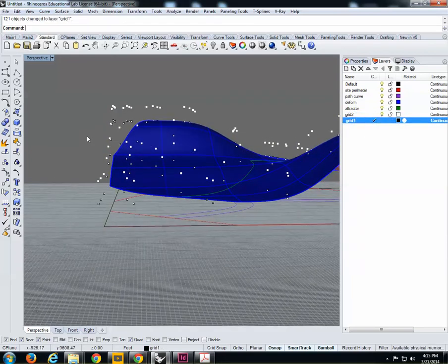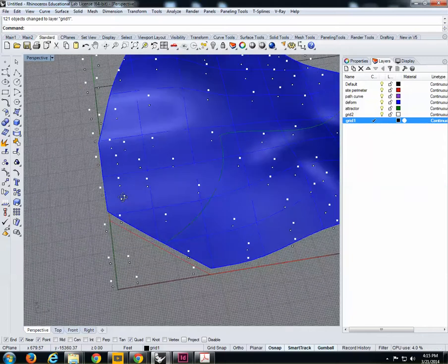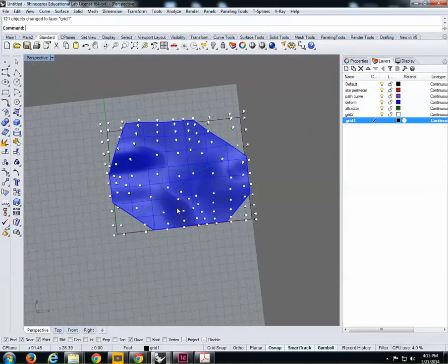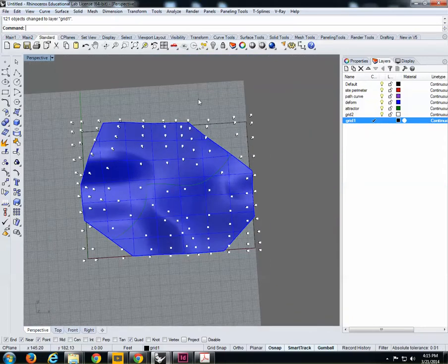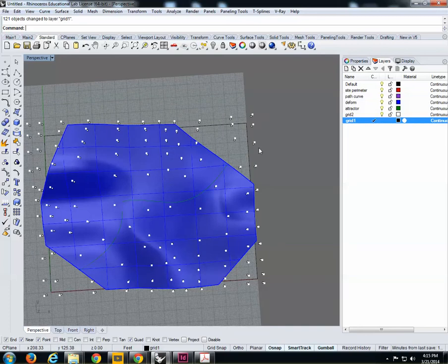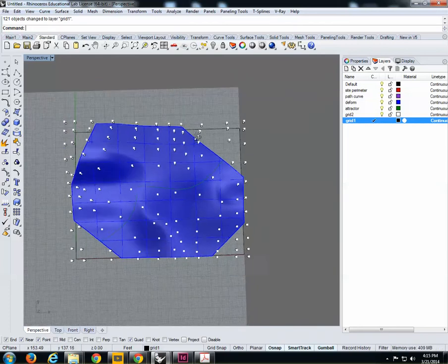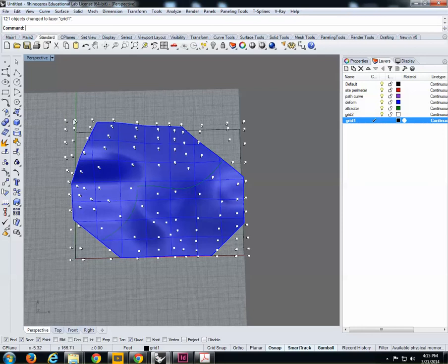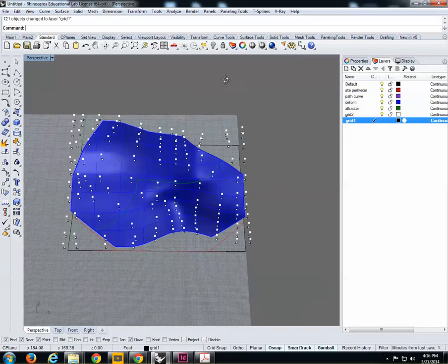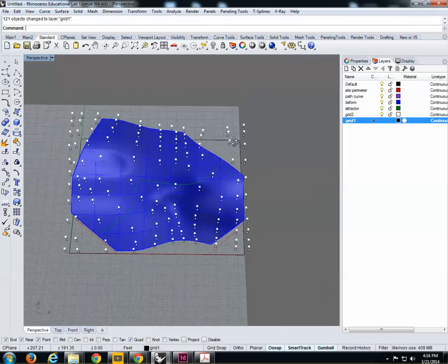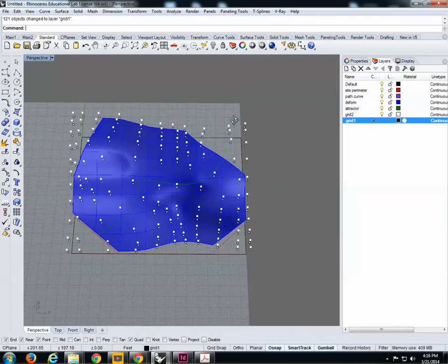Nice. So the next step, it seems, what we are trying to do is to basically get rid of these extra points that are not really describing our surface. So paneling tools go ahead and work with the overall surface that generated this trimmed surface. That's why they end up giving you points of a full rectangle. You don't want that resolution, so you will need to go ahead manually and delete them for now.